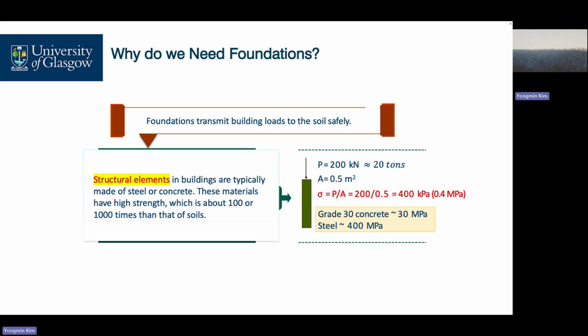Then you have this interface of geotechnical and structural, which is the foundations. Considering your cross-sectional area, the pressure acting on this part is around 400 kilopascal. This 400 kilopascal transmits laterally and vertically to the soils.